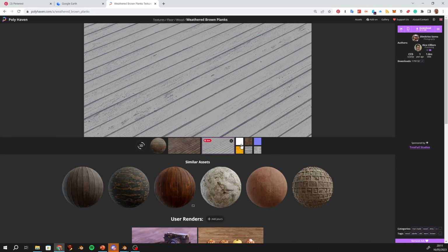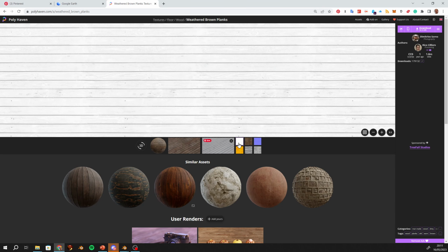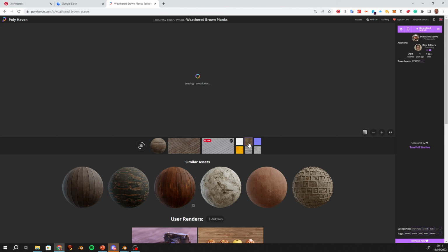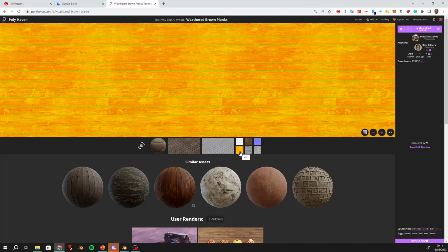But you also see here the AO, the ambient occlusion map you get, the diffuse map you get, the normal map you get, and here is this ORM map. You think this is not what you're going to see. You don't get an orange floor. Actually, these are three maps in one. This is the ambient occlusion plus the roughness plus the metal. They are in three different channels of the texture, the red, green and blue channels. They store a different texture in each channel, and that's why it looks this way.